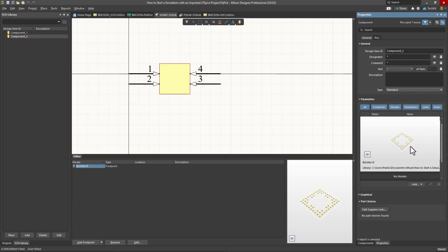You can click to preview a PCB footprint. How do you do this? Well, you can associate different files with the schematic symbol: simulation, an IBIS model for signal integrity and high-speed digital interfaces, PCB 3D, signal integrity, footprint. See this footprint right there. So you associate all this information with the schematic symbol, and the schematic symbol ties it all together.